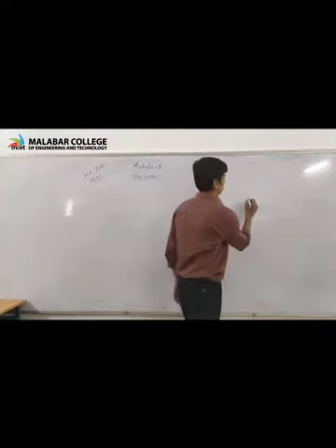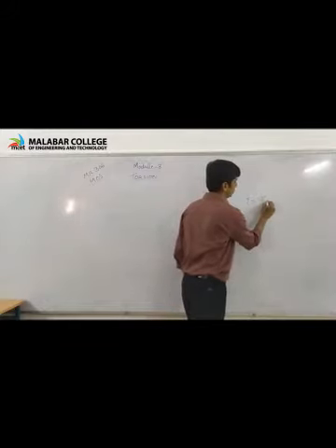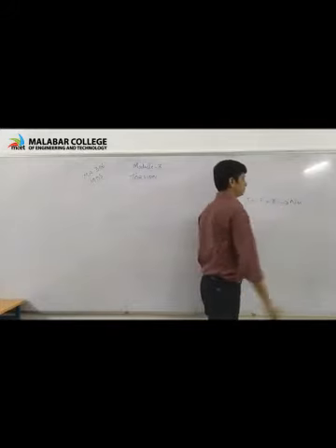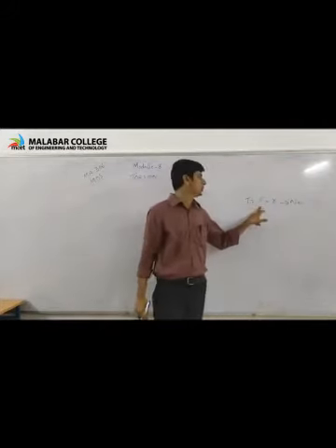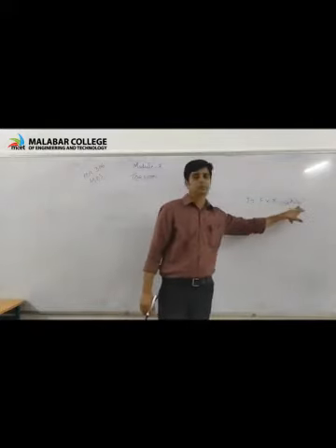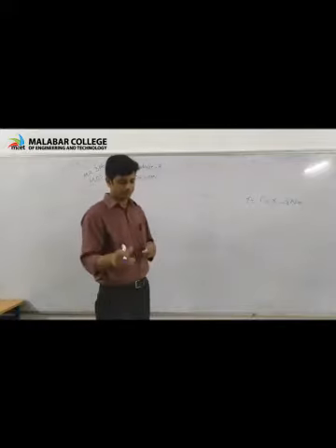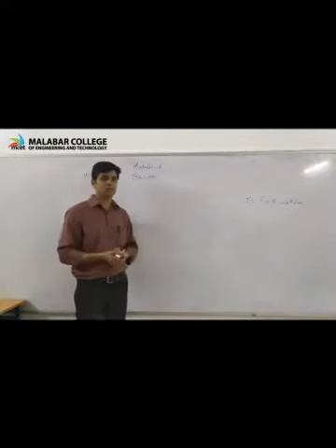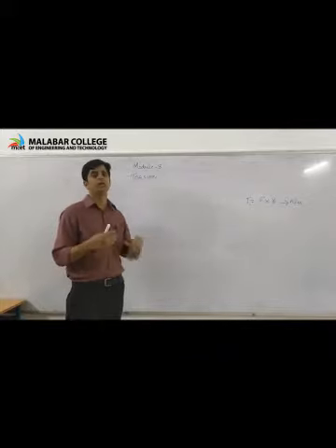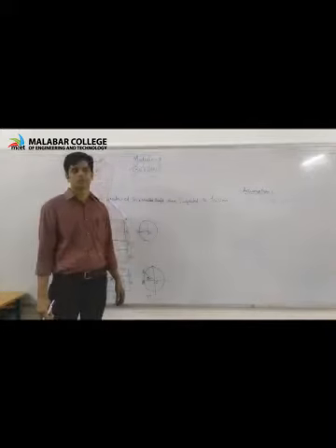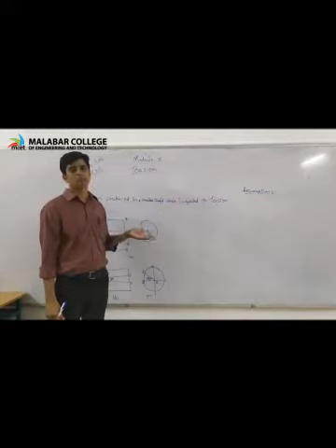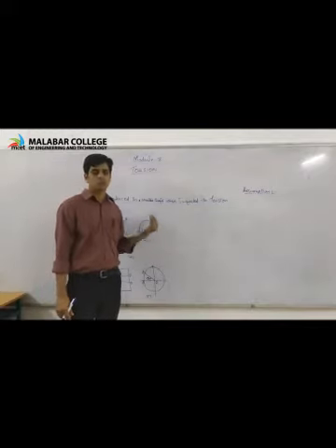Torque T is equal to force into perpendicular distance. Its unit is Newton meter, since the unit of force is Newton and distance is in meters. Torque is nothing but a twisting moment acting on the shaft, and this twisting moment causes shear stresses and shear strains on the surface of the shaft.